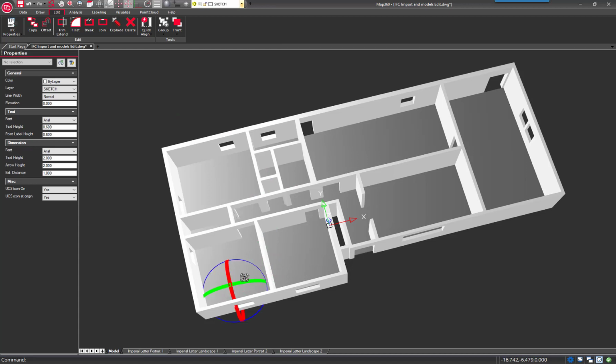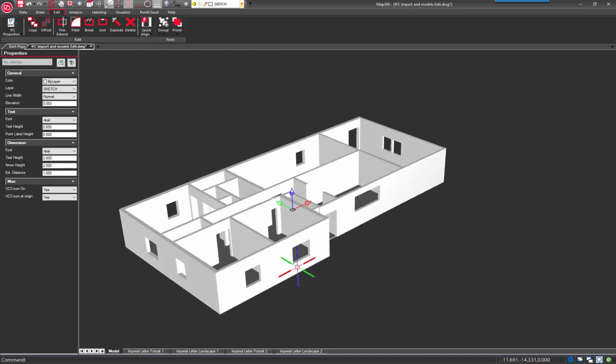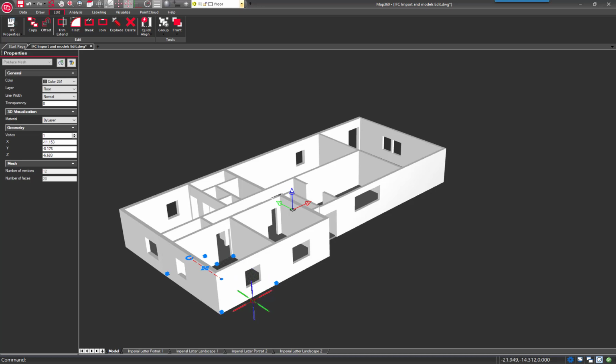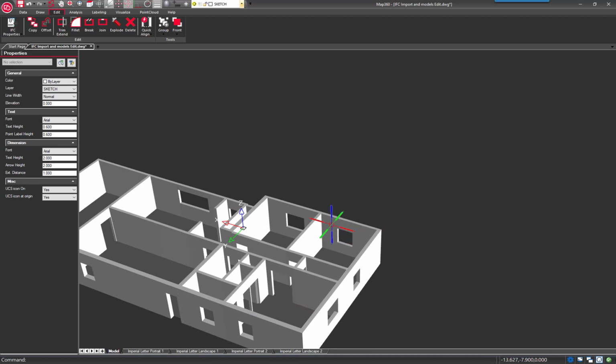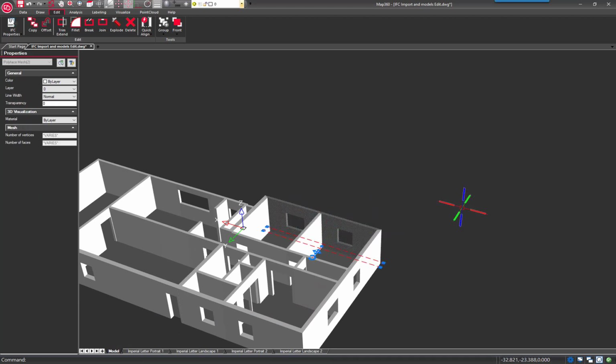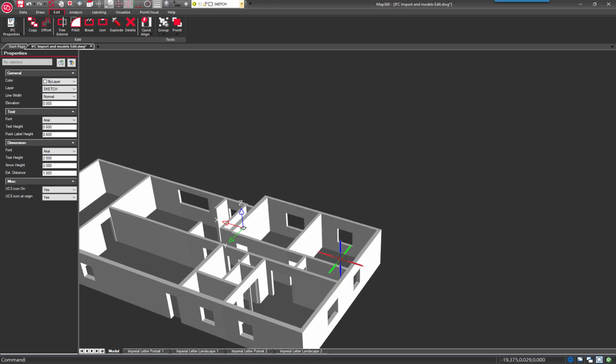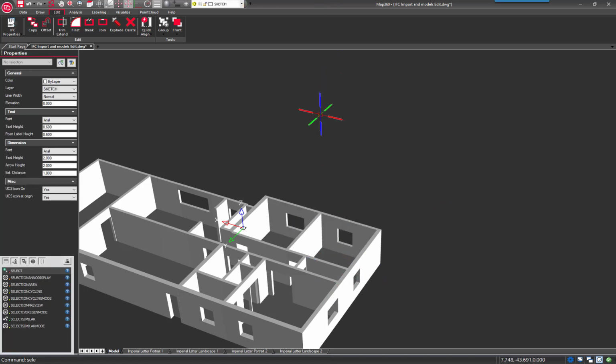Next thing I'm going to show you is how to change the transparency on an object. In this case, let's say this wall here on the front of this building. When you go to select an object from a side view like this, it'll often select the object behind, and a way around that is to rotate your object so that there's nothing behind where you're picking on it. So now I can select that wall.